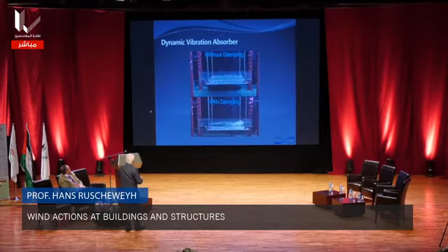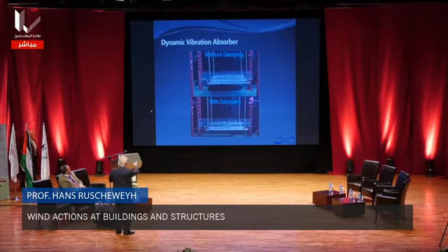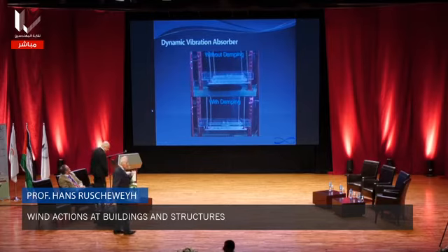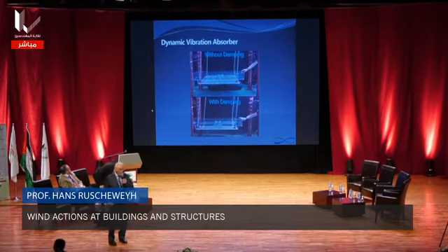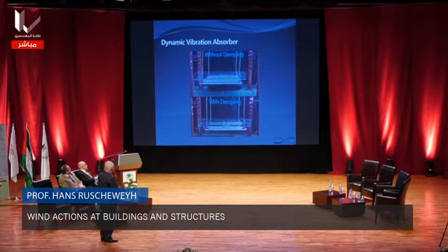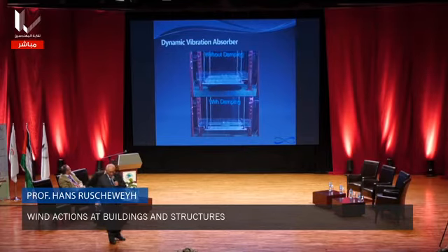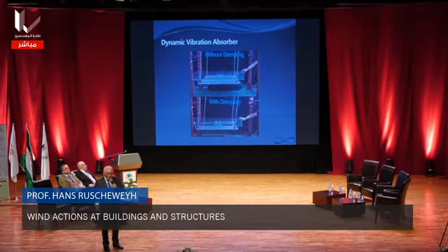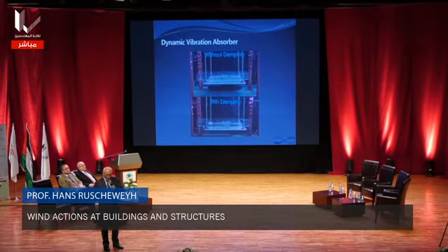You see, the lower box after 2-3 amplitudes is at rest, and the upper one without liquid is vibrating. It's the same model, only put together in this figure. It's a very effective damper system, and it is very cheap. It's only a box with water, or an anti-freezing liquid, because in wintertime it can be frozen.